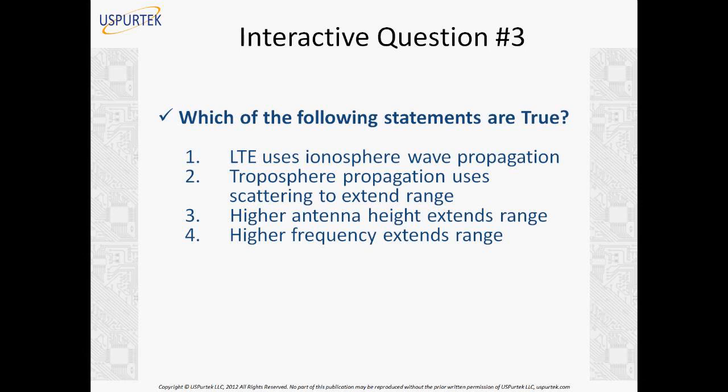Which of the following statements are true? LTE uses ionosphere wave propagation. Troposphere propagation uses scattering to extend range. Higher antenna height extends range, and higher frequency extends range. So which one is true? Well, number one is not true because LTE 4G wireless does not use skywave propagation. Troposphere propagation extends range. Yes, that is true. We just talked about that. Higher antenna height extends range. Yes, that is true. Higher frequency extends range.